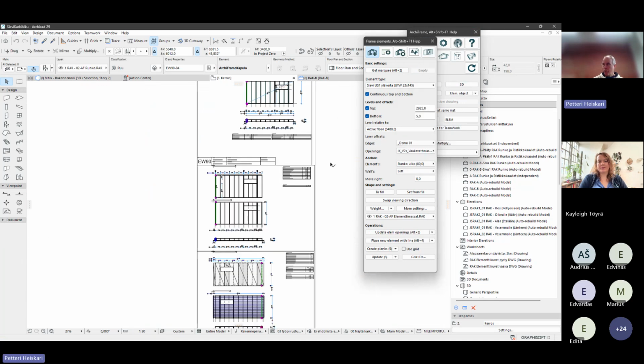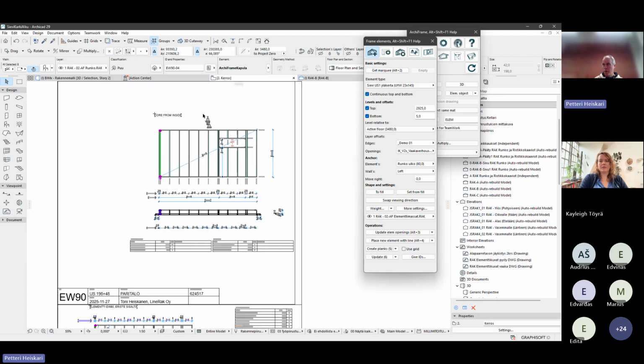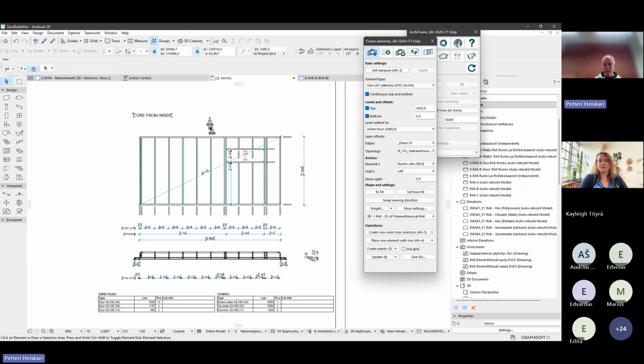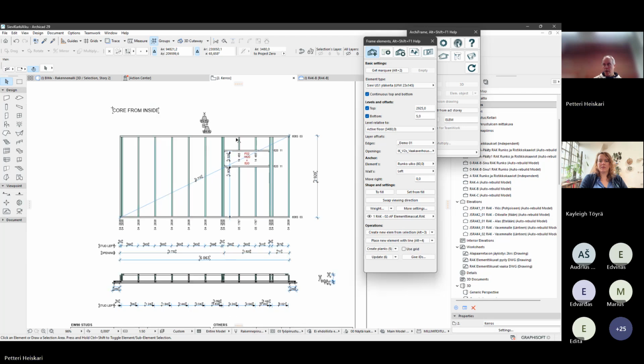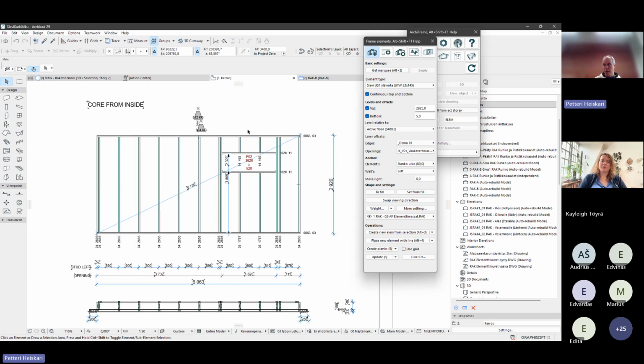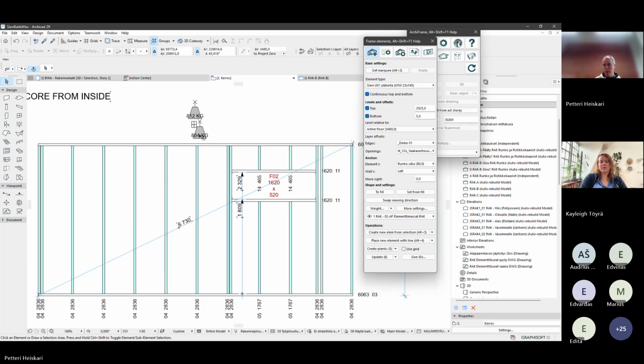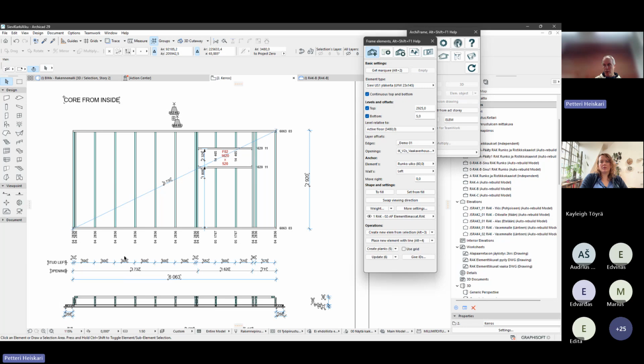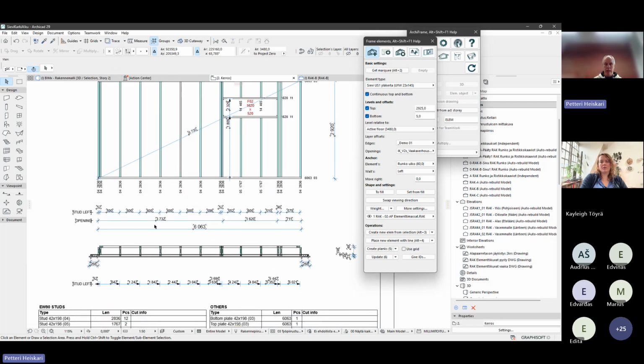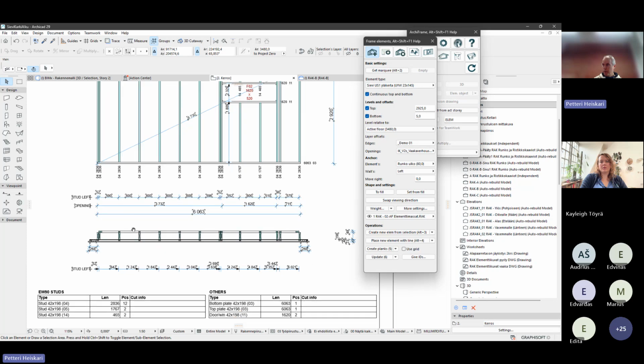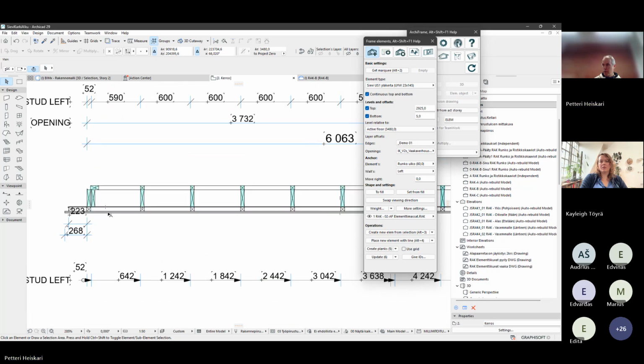Then the most important end results of ArchiFrame and this element design work are these element drawings, 2D documents. What we have here with this first projection is only the main framing looked from inside, its weight and center of gravity without windows, and then with windows. Then all these automatic dimension lines based on the settings, ArchiFrame settings, top projection, cladding, the airspace, and so on.